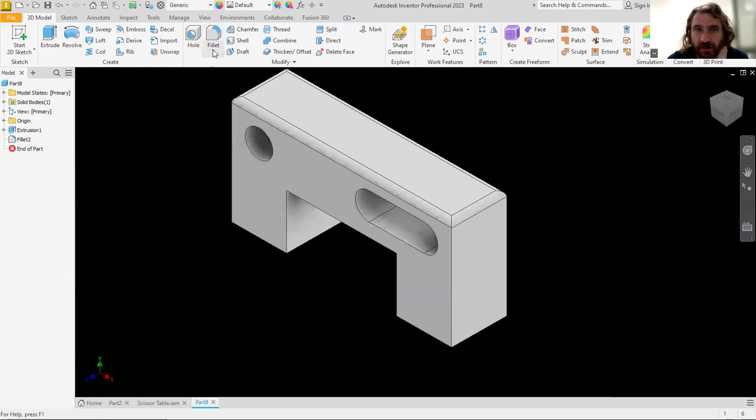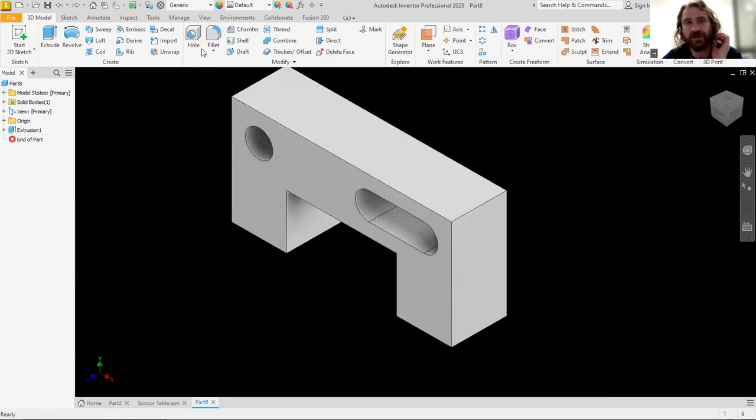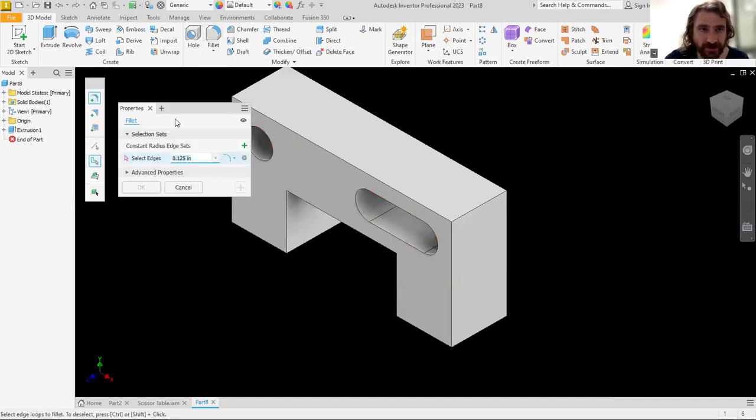There's our fillet there in the browser and we're good, right? Let's undo that. Control Z is our friend. And go back to fillet. So there's a lot of things you can do here, adding variable radius, corner setbacks. But again, the most commonly used item here is the constant radius edge. And then it's just determined by whether it's just going to be one edge, whether you need to select a loop, or whether you want to select a whole feature.